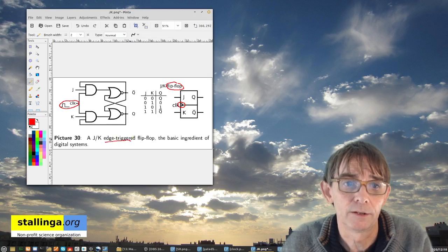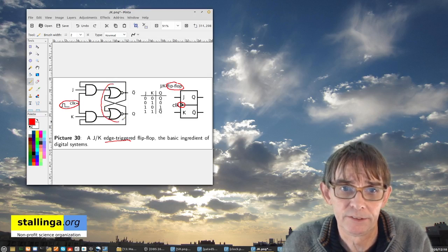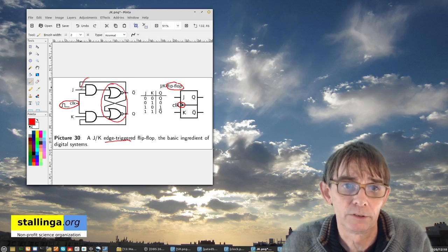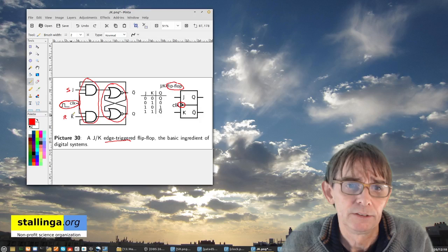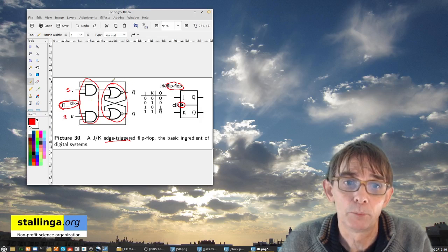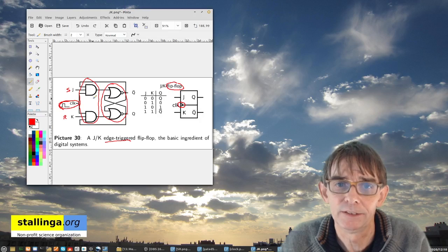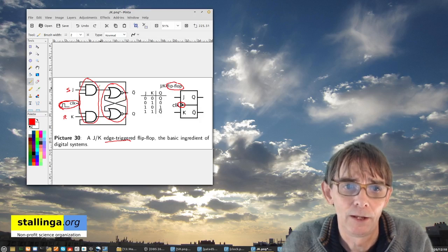Edge triggered. And the idea with the JK flip-flop now is that we have this set reset flip-flop, but we put a stage before it which is ANDing the SR, which are now called JK. S, set and reset signals, we are ANDing them with the gate, the clock, and we are actually putting another feedback, that the output is also fed back here to the input of the AND stage.